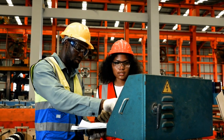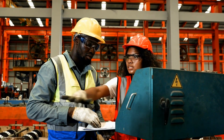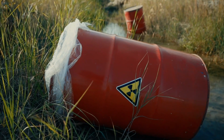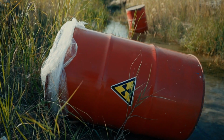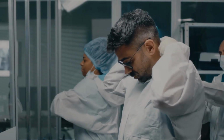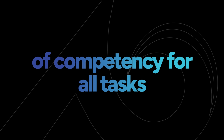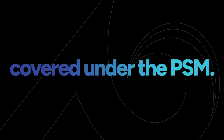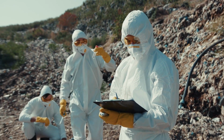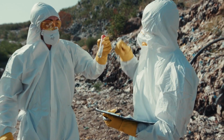OSHA requires that each employee involved in or newly assigned to an operating process be given an overview of the process and training in its operating procedures. The training must emphasize health and safety hazards associated with the process, emergency operations, and safe practices related to the employee's job tasks. The training must also include a verification of competency for all tasks the employee will complete covered under the PSM. Refresher training must be provided at least every 3 years to each employee involved in operating a process to ensure that they understand and can implement up-to-date practices.